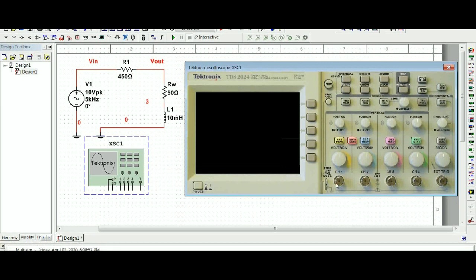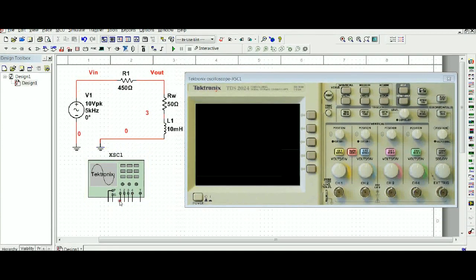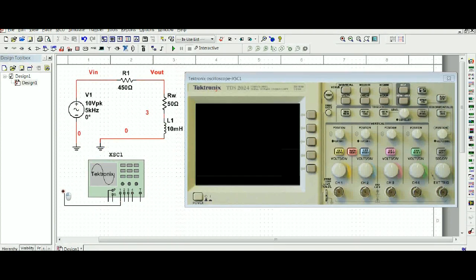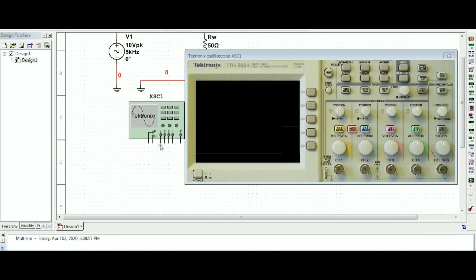In a physical circuit, you have to connect this, or your signal is going to be overridden with massive amounts of 60 Hertz from the powering in the room. So that's something you have to remember: in simulation you don't need it, and other than that you do. So let us connect channel 1 to this point and channel 2 to this point, and I can just wire that in here. Oops. Here we go, and I'll just go up the side here, or not. Let me try again.